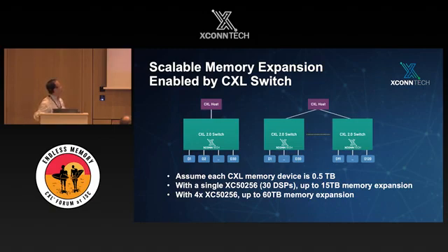All these hosts are supporting CXL 1.1, and the memory devices are single logical devices, SLD, as of today. However, in the future or next year, we do see these hosts going to 2.0, and the memory devices going to support multiple logical devices, MLD. And our switch works in both cases.